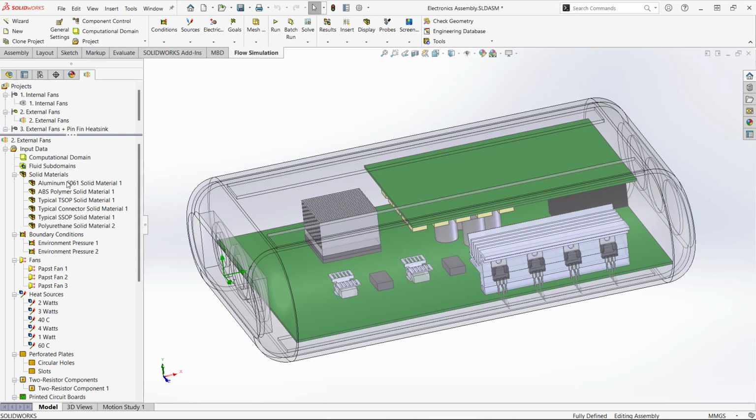The next major thing that's going to be done with a thermal analysis is you want to assign how you're going to introduce your heat energy to the system. Now, there's a very generic way to do that and some very specific ways. The more general way of doing that is by using heat sources. So you just do a right click and you say Insert Surface Source, or you can say Insert Volume Source.